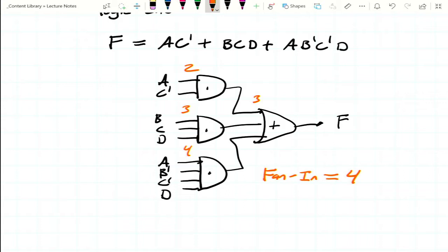And it turns out that due to a number of constraints related to the realities of actually building these circuits in a factory, depending on the technology you're using to implement your logic, depending on the types of transistors, the node size, right? You may have heard things like 4 nanometer versus 6 nanometer. Depending on those factors, maybe the factory is only machined for designing 2 input NAND gates or something like that. There are a number of reasons why you might be faced with a limitation that says you can only have gates of a certain fan-in or logic circuits of a certain fan-in. And you've got to deal with that.